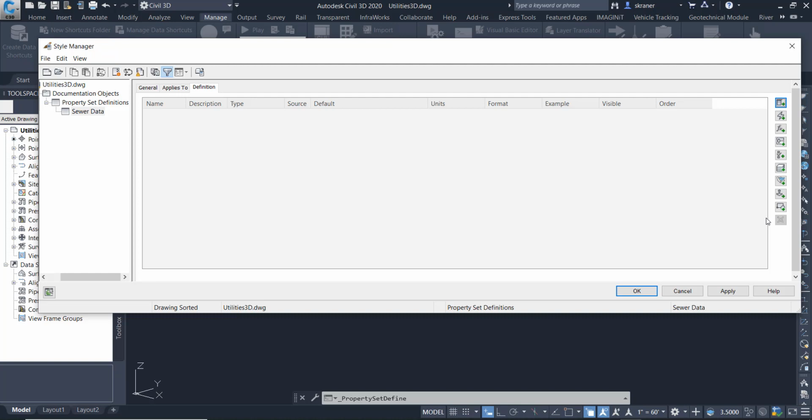There are several definition types that we can choose by selecting these icons. Some obtain data from the physical characteristics of objects, such as their volume. Others utilize formulas, location information, classification definitions, material property definitions, and several other types of information. We'll be using the Add Manual Property definition to attach user-defined information to our utilities. Select this top icon to enter a new manual property definition.